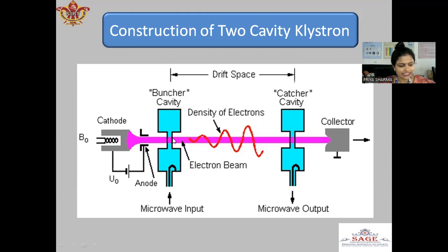At this instant, the electric field across gap A is 0, and an electron which passes through gap A at this instant is unaffected by the RF signal. Let this electron be called the reference electron. The electron which comes from here is known as the reference electron, and it travels with an unchanged velocity.